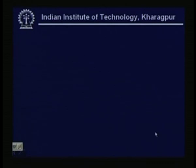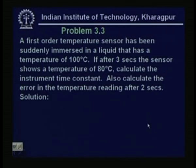Now, let us go to the problem number 3. It is telling that the first order temperature sensor has been suddenly immersed in a liquid that has a temperature of 100 degree centigrade, and after 3 seconds the sensor shows a temperature of 80 degree centigrade. Calculate the instrument time constant, also calculate the error in the temperature reading after 2 seconds.